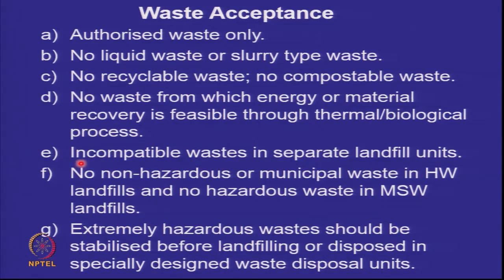If you are having a hazardous waste landfill, you get waste from different industries, and fires and explosions at hazardous waste landfills are not unheard of. So if you have incompatible waste, one which will ignite the other or cause a reaction, then you have to store them separately in separate landfill units. You can't store municipal solid waste in a hazardous waste landfill, and hazardous waste in a municipal solid waste or a non-hazardous waste landfill.